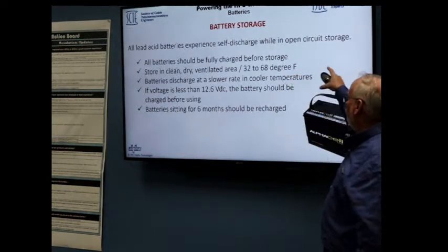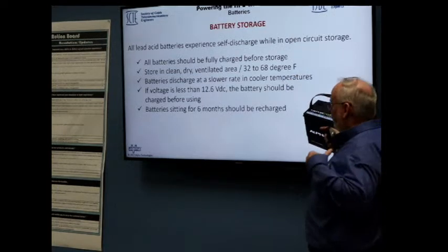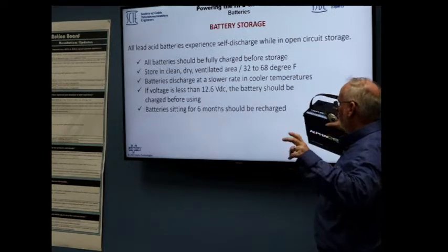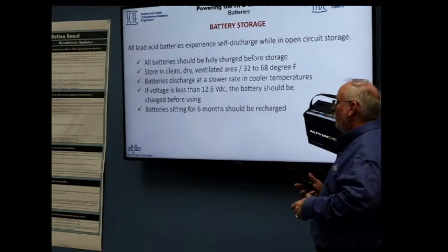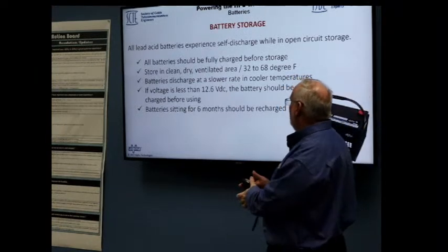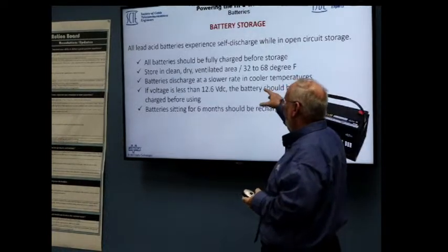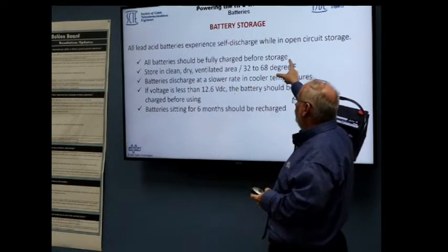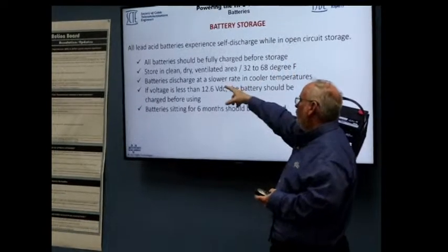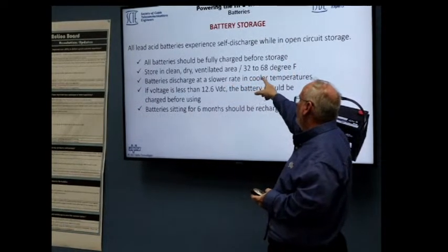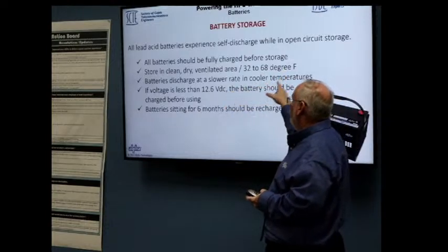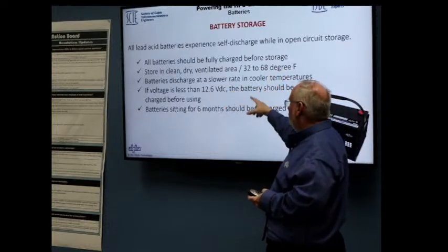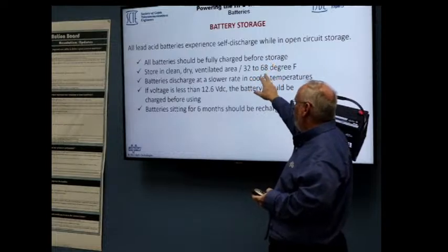Lead acid batteries experience self-discharge. This is one of the issues with lead acid batteries. If you don't charge them, they will self-discharge. They have a very high current delivery, and with that, they self-discharge very well. All batteries should be fully charged before they're put in storage. Store in a clean, dry, well-ventilated area, 32 to 68 degrees. Batteries discharge at a slower rate, hence the reason. Don't freeze them, but don't get them too hot either.